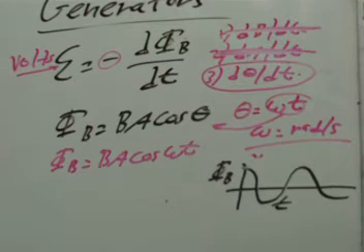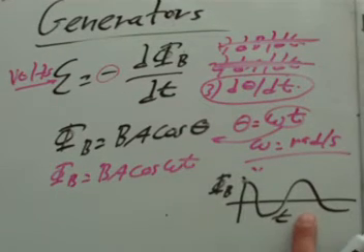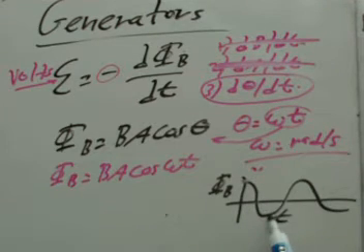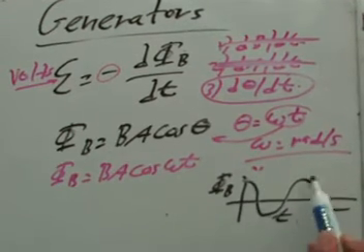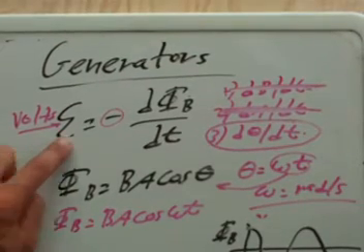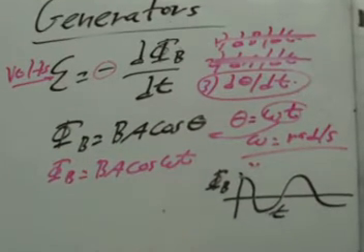And the point is as follows. Do I have a magnetic flux that is changing with time now? Yes or no? No matter how messy my sketch is, is it changing with time? The answer is yes. At one moment it's up, at the next it's zero, next moment it's down, then it's up. As time goes on, this thing's going up and down, up and down. And remember, that's what I need in order to get volts out. I need a time derivative of magnetic flux, and it looks like I have it. By making the angle change, I have it.